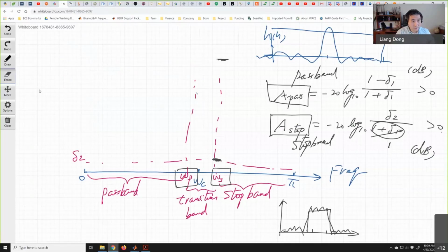Because you just said you're using an FIR filter. I'm using an FIR filter. FIR filter H omega, we have only B omega. We don't have over A omega. This is a polynomial in the denominator. But in an FIR filter, this goes to 1. I don't have poles. I only have 50 zeros here.